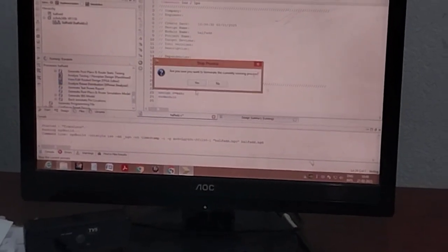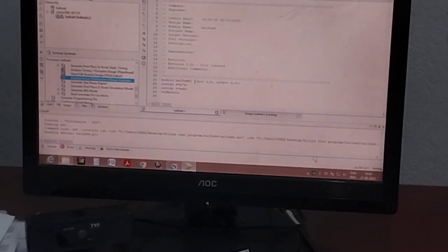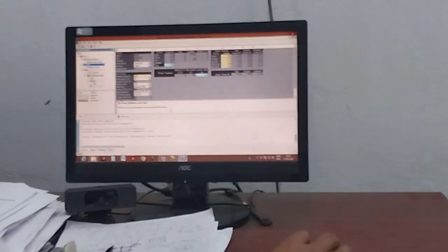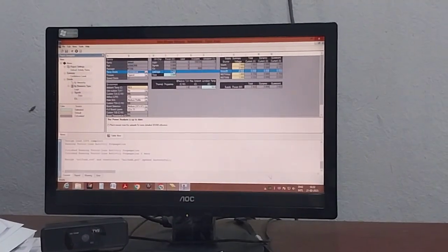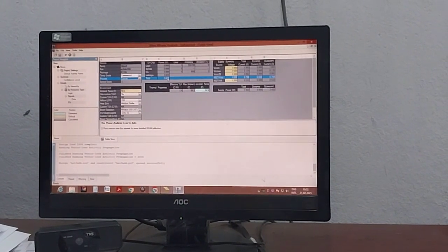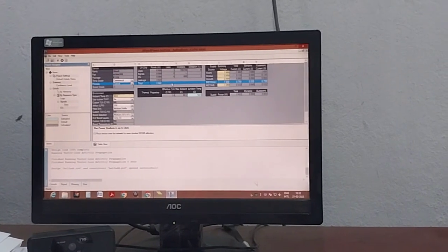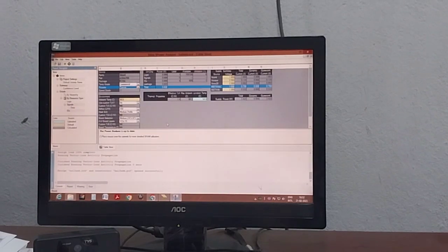You can stop, or sometimes it is showing some. Okay, you can stop. The XPower Analyzer output, you can see a new window will come. Here you can see the power consumption information. The logic power is 0, signal power is 0. Basically it is showing the leakage power. The total power consumption it is showing is 3.422 watt. But that is not accurate power consumption, okay.